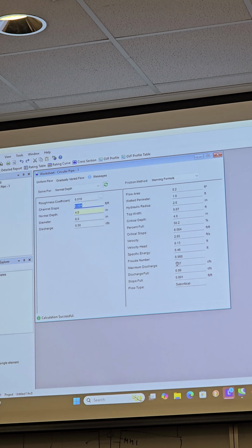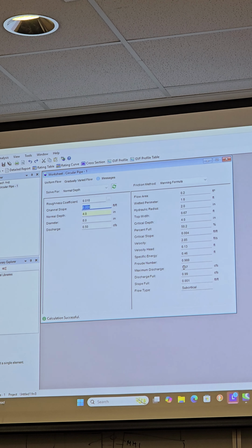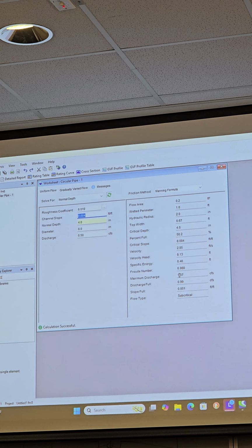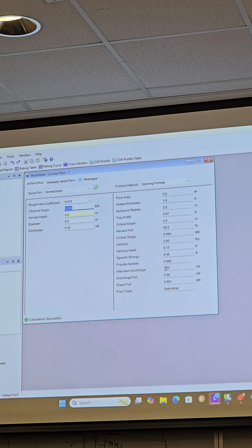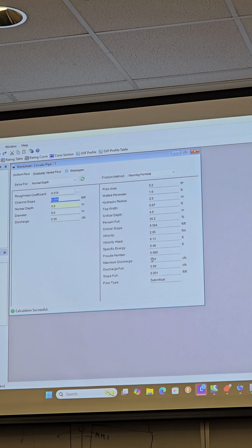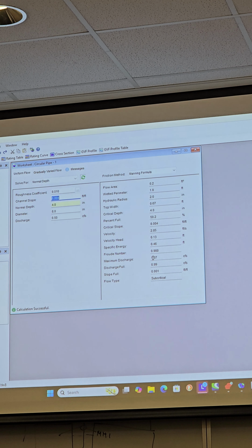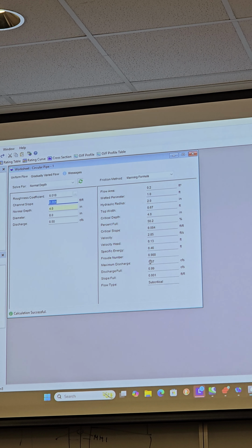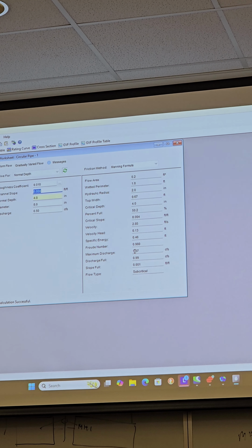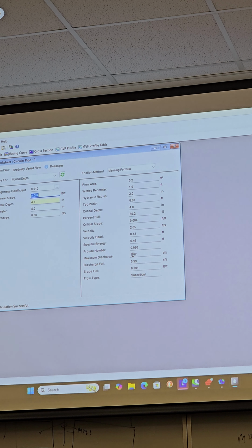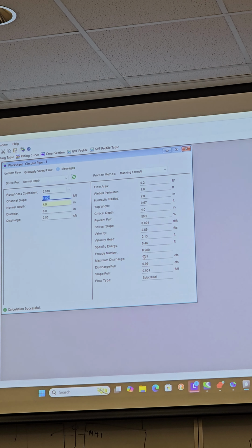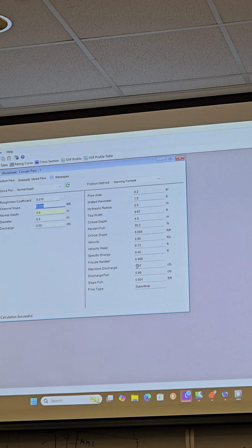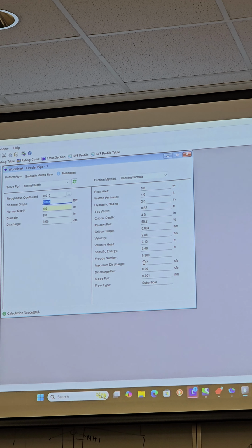How is the normal depth related to 8? Is that 75%? Like it has to be 75% of the 8 inches? Yeah, so to be more technically correct, it's 75% of the cross-sectional area of the pipe. So I said 6 inches just to keep it simple, because you have an 8-inch diameter pipe, so 6 is 75% of 8. But as long as your depth is 6 inches or less, that pipe size is appropriate. And 8 is just what we're going to use, that's the minimum pipe size.